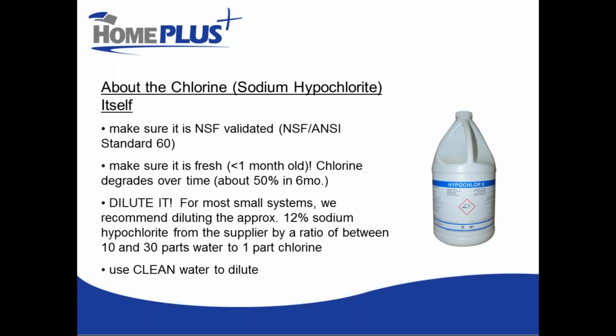And when you're doing your dilution, use clean water, especially water that has high levels of iron, manganese, hardness, or organics can be problematic. Hard water deposits will cause fouling of the screen on your foot valve. Iron and manganese will cause precipitates that will build up in the solution tank. And organics have chlorine demand and can form disinfection byproducts. So we want to avoid all of those things. Use nice clean water to mix or dilute your chlorine.